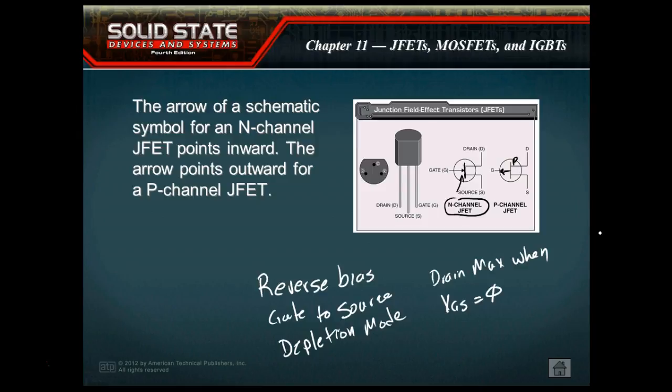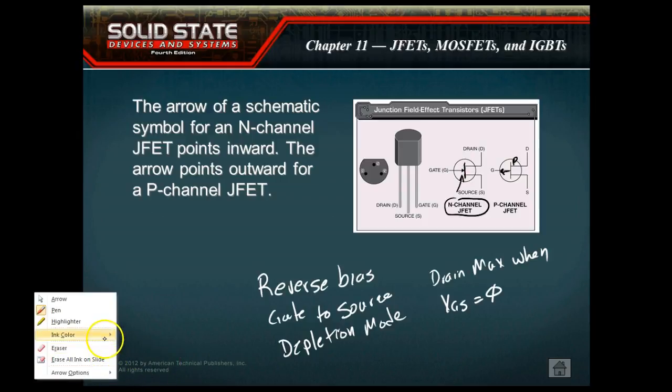Now remember, on FETs, your drain current and your source current are exactly equal to each other because it flows through a channel. And the only thing we have through the gate lead is leakage current, which is so small that we can't measure it.